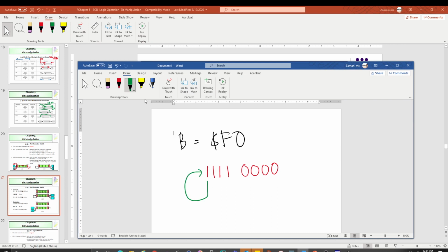So right now the LSB value is 1, and the rest will be moved to the next one, 0, 0, 0. And then the LSB here is going to be copied to X and C. This is the first arithmetic shift right.